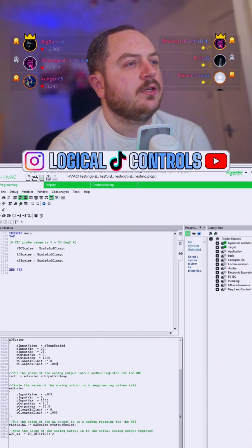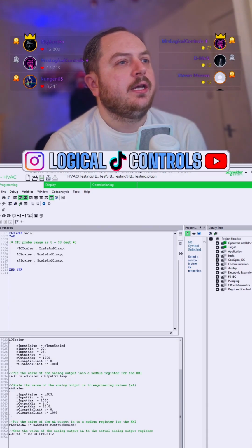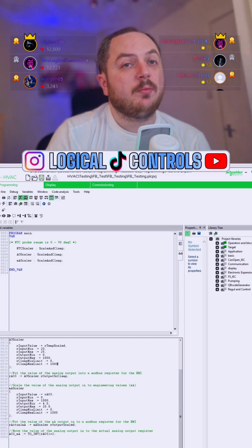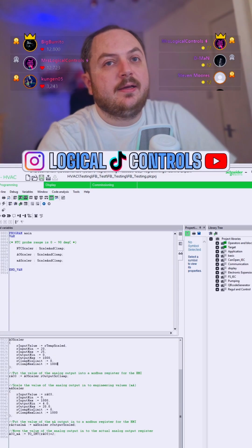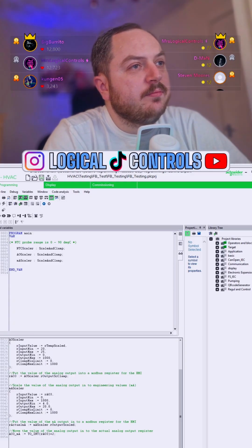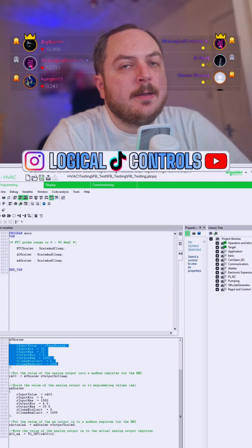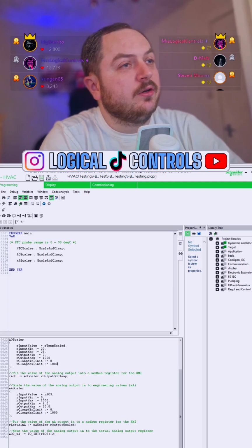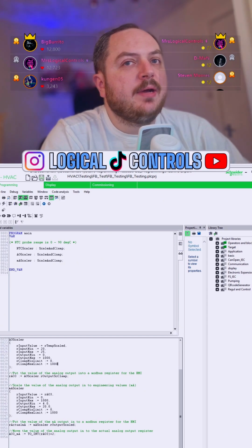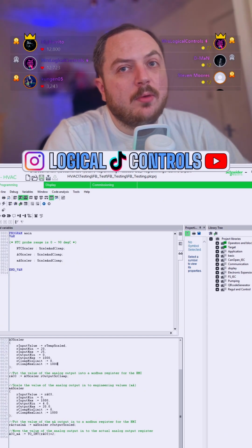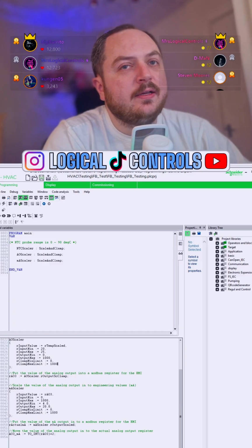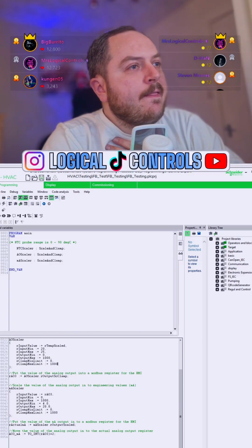Is Modbus safe when it comes to cybersecurity? Yeah, I would say... It hasn't really got any security. Modbus TCP, that is. It doesn't really have any security behind it, not anything modern anyway. I'll just say no. I think the answer is no. In fact, David, you've already let him know. I would suggest never putting a Modbus TCP network on a site's LAN or anything like that. Keep it separate. Always keep it separate.